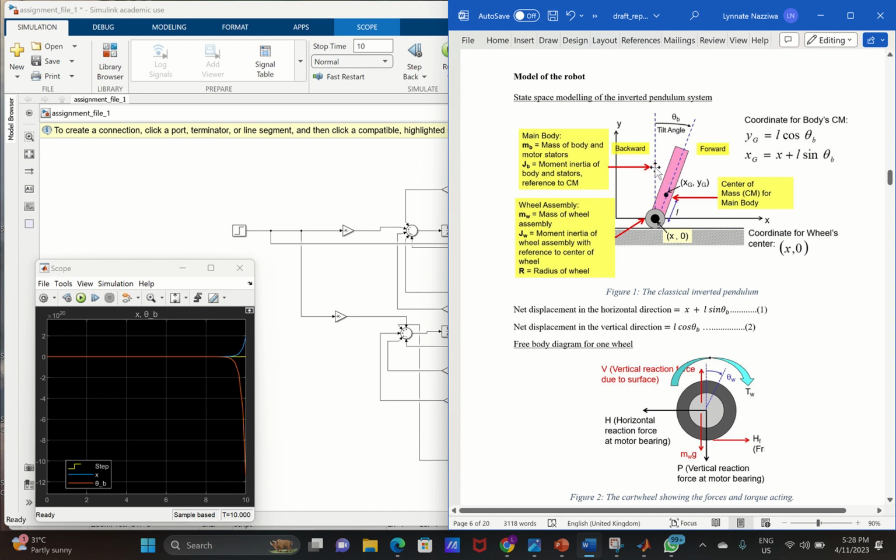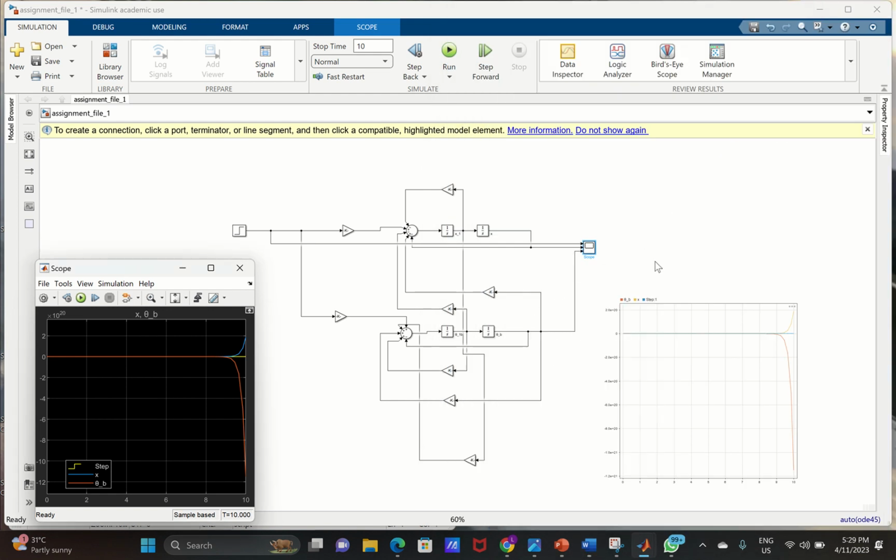So when the tilt angle is reducing, the robot is going to be moving in the X direction with a reducing value. For both directions, the values grow exponentially big with time since we do not have a controller in the system. Hence, a fundamental reason why we need a control system, and that explains to us that a balancing robot cannot work unless it has a control system.